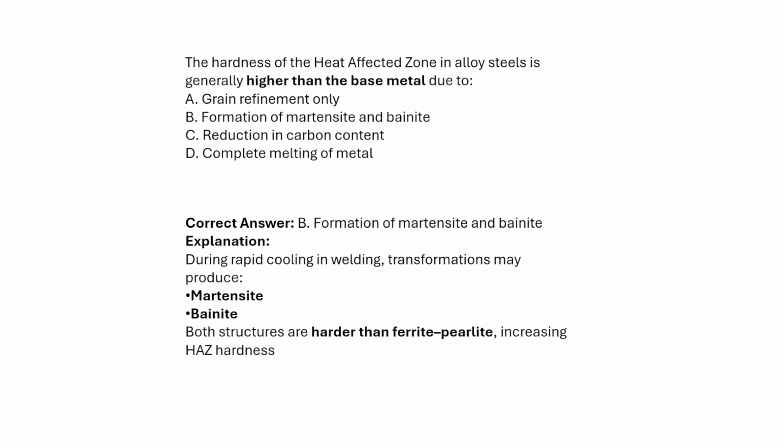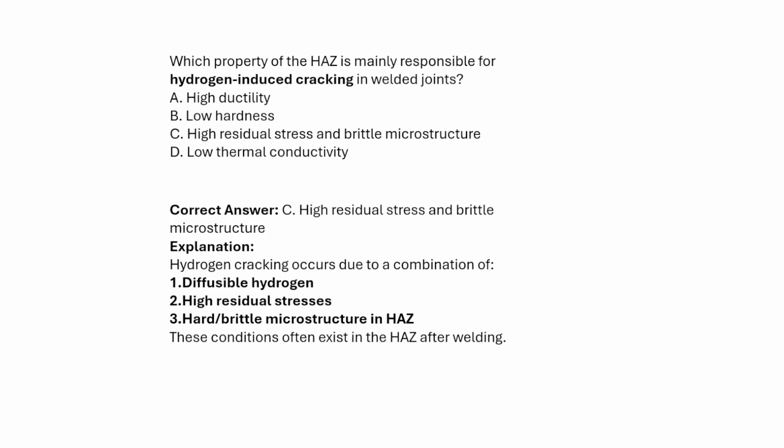Okay. During the rapid cooling in welding, the transformation may produce martensitic and bainitic phases. Both are structurally harder than the ferritic and pearlitic phases. That results in increasing the hardness of the HAZ. Okay.